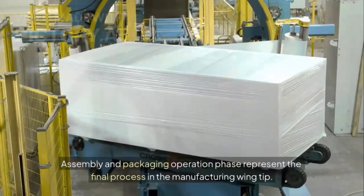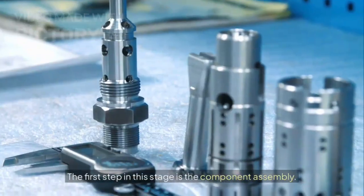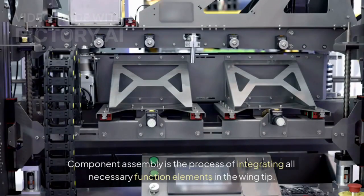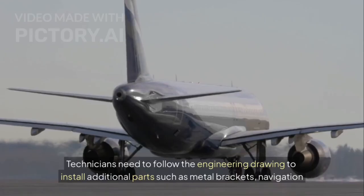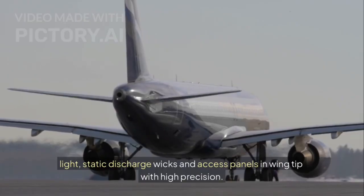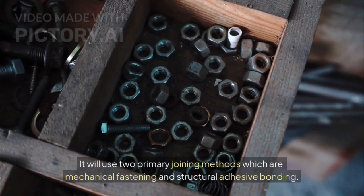Assembly and packaging operation phase represents the final process in manufacturing the wingtip. The first step in this stage is the component assembly. Component assembly is the process of integrating all necessary functional elements in the wingtip. Technicians need to follow the engineering drawing to install additional parts such as metal brackets, navigation light, static discharge wicks and access panels in the wingtip with high precision. It will use 2 primary joining methods, which are mechanical fastening and structural adhesive bonding.